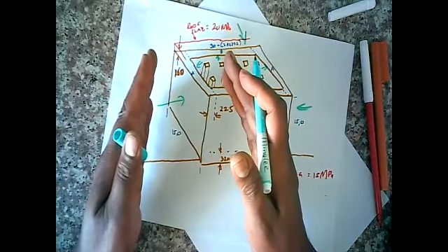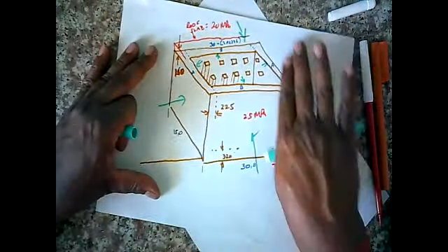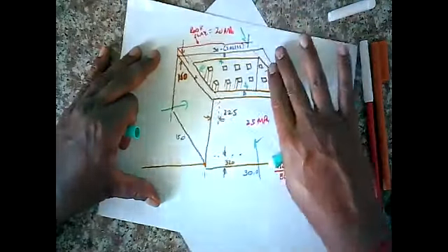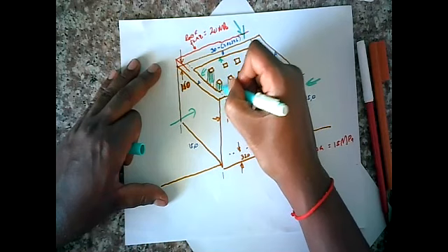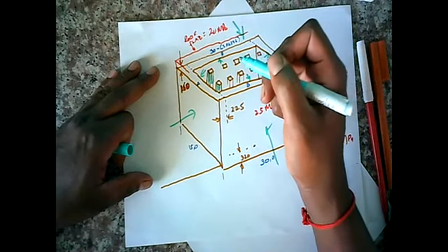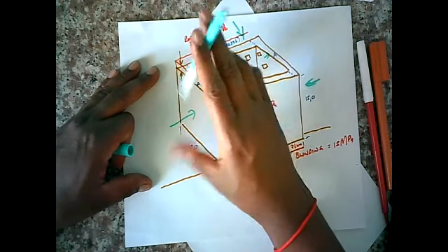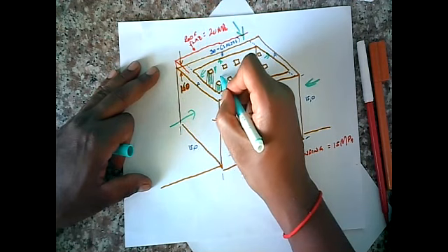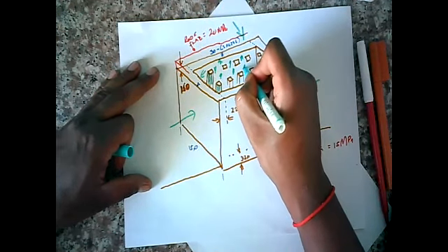And we're using shuttering. So I need to find the area of all this, that inside, and also all the panels here for our columns, 4 sides. All right. And then when we finish with that, we also need shuttering for the roof, basically, to hold up the roof for it to set.